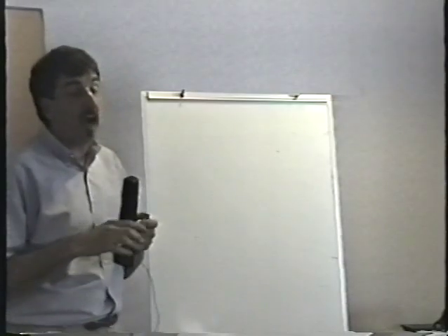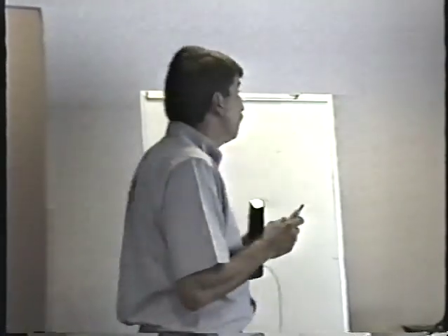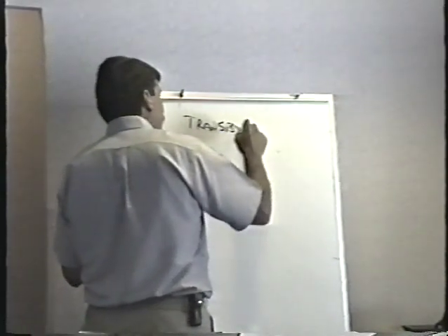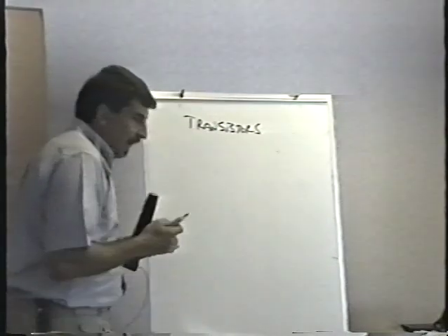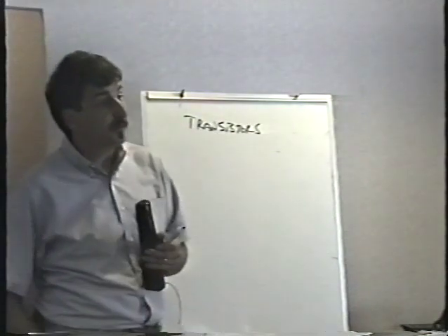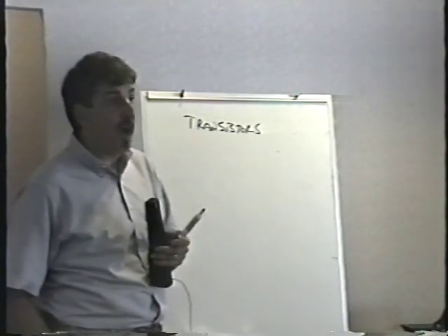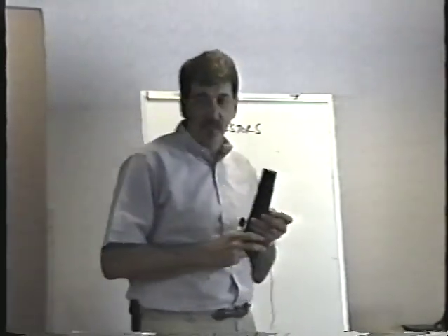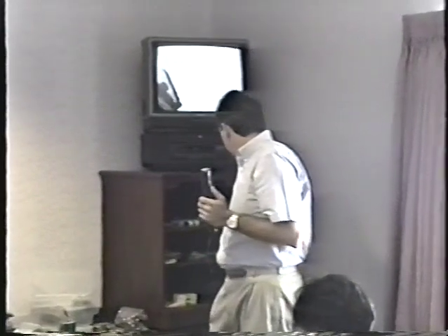And now we're going to start on a quick look at transistors, and we'll finish up with transistors tomorrow. I see lots of transistor failures, especially in power supplies and monitors and pinball machines. Very common. Much of the time, if you have a problem that's not a capacitor, you have a semiconductor failure. And transistors are real common failures. I see lots and lots of transistor failures.